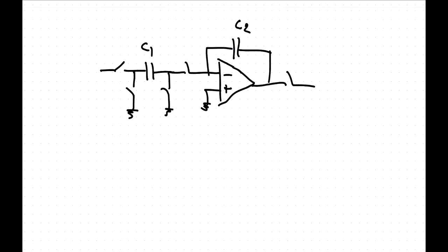Let's have a look. So if we're doing clock phase 1 there and 1 there and 2 there and 2 there, and look at clock phase 1, then it's almost the same as what we had before. Now it doesn't matter what the capacitance on these nodes here are. In one phase that node is shorted to ground, in the other phase it's at virtual ground, so this node voltage doesn't change. That node here, the capacitance to ground here is just going to be charged to whatever that voltage source is. It doesn't change the charge flowing in here.